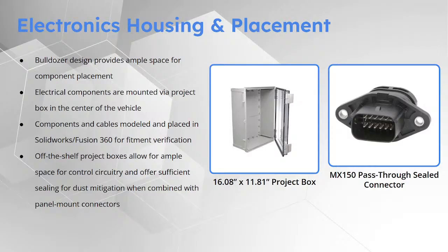Molex connectors themselves do have built-in rubber gaskets in all the connectors. They also have plugs to fill in any gaps where you maybe don't have a wire or a terminal, to keep dust, and in a more general sense water and debris, from getting in there. So big fan of Molex connectors. As far as high current applications, we are looking at Anderson connectors too.